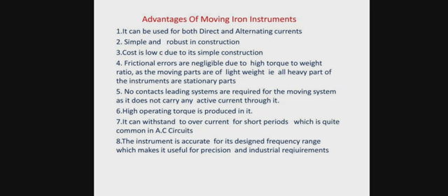Then coming to the advantages and disadvantages of moving iron instrument. First, we will discuss the advantages. It can be used for both DC and AC currents. The moving iron instruments can be used for both DC and AC currents, or we can say the instruments are suitable for use in AC and DC circuits.